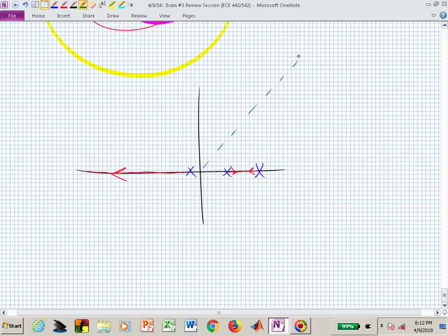Let's say that's the centroid right here, sigma sub a, and this line is supposed to be 60 degrees, and those asymptotes symmetrically divide the entire z-plane. One branch goes off at 180, one goes off at 60. Those two are separated by 120. If I split 360 3 ways, the angle between those asymptotes is going to be 120. So this one is minus 60.